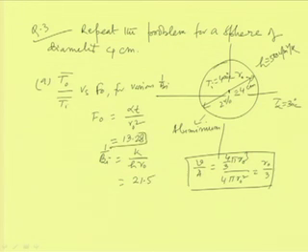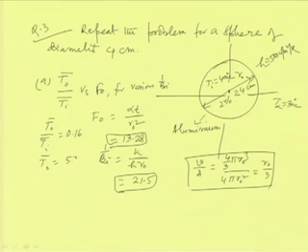Once we know the value of 1 by Biot, we can find T naught bar by T I bar, and interestingly this factor becomes 0.17. The values are gradually reducing, and T O bar becomes 59 degree centigrade, so T O is equal to 89 degree centigrade. So we get the center line temperature as 89 degree centigrade for this case.